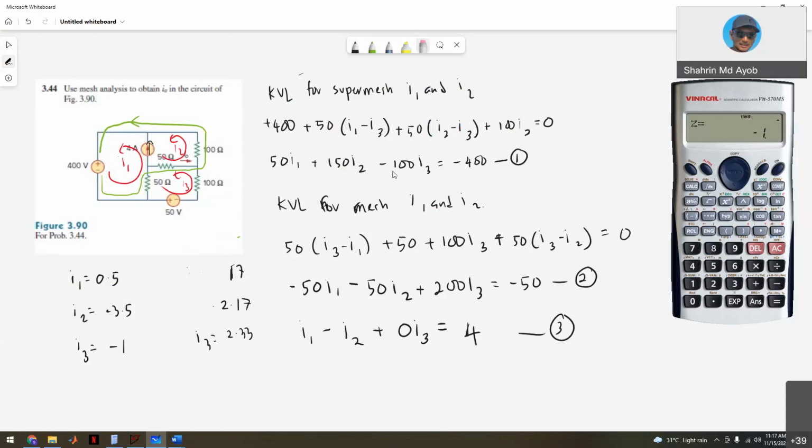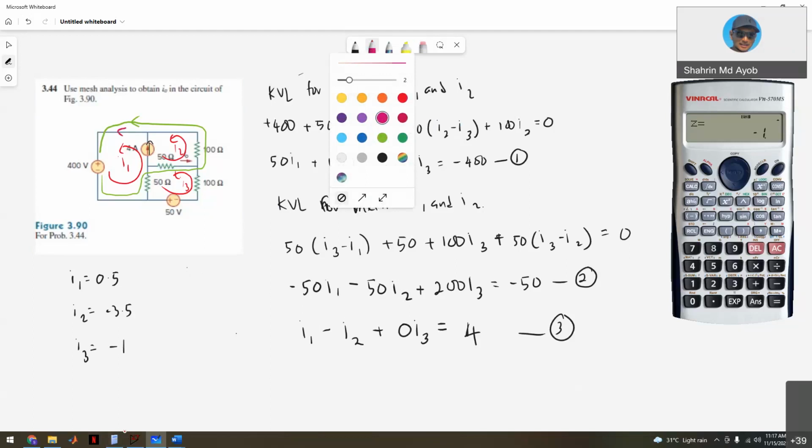Okay, so to highlight what Hussein has raised, the issue is actually on the sign. So actually, the answer is correct, and the sign, as you can see, is actually 0.5, meaning the direction of the mesh current that you assumed at first, during the definition of the current direction. So I1 is actually flowing in this direction. Your current I1 mesh current is actually the branch current.